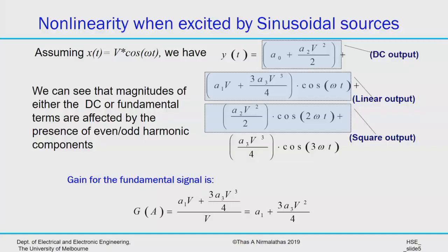So once a circuit has a nonlinearity, even the gain or multiplier is no longer determined just by the first order coefficient A1, but the third order term also adds power to the fundamental by way of mixing. And what happens is that the gain, which links the input voltage to the output voltage, is now suddenly a function of your input magnitude. That means as you increase your signal at the input, your output gain is changing. Why? Because there is a constant energy transfer from your fundamental signal component going into the circuit into all the other higher frequency components of 2 omega t, 3 omega t, and so on.